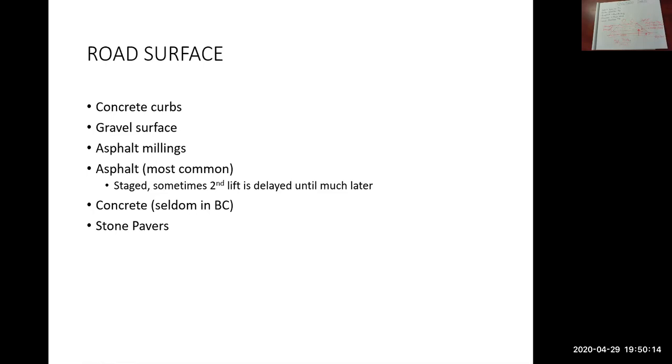There are machines that have big teeth underneath them on a big wheel, and they dig into the pavement, and the wheel is spinning, and it grinds up the pavement into small pieces that are approximately 19 millimeter and smaller. Those are called millings. That's also an optional road surface material. Of course, it's not used in cities. Maybe it's used for driveways, gravel pits, that sort of thing.